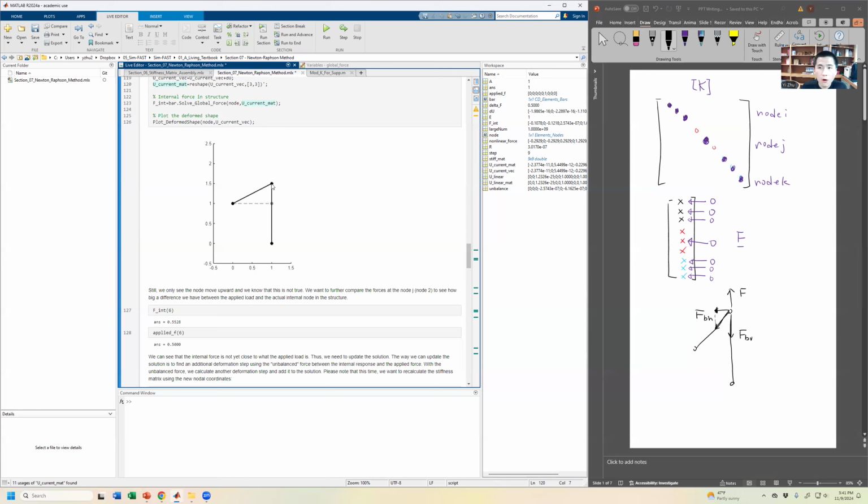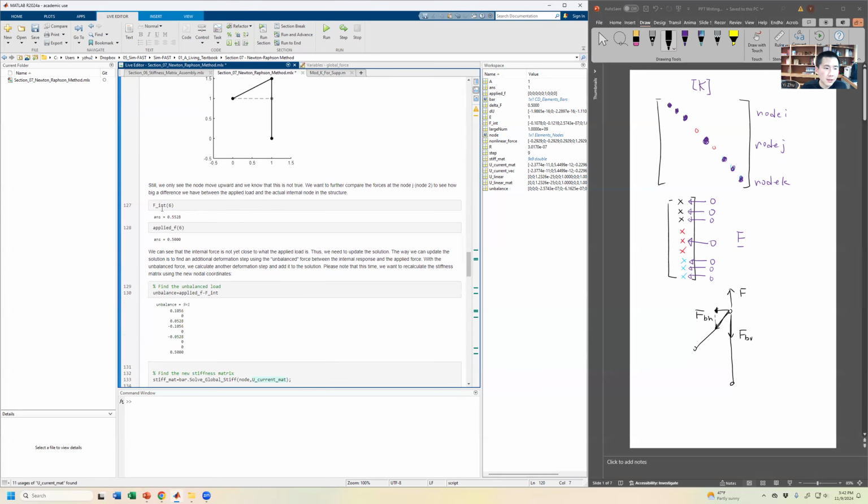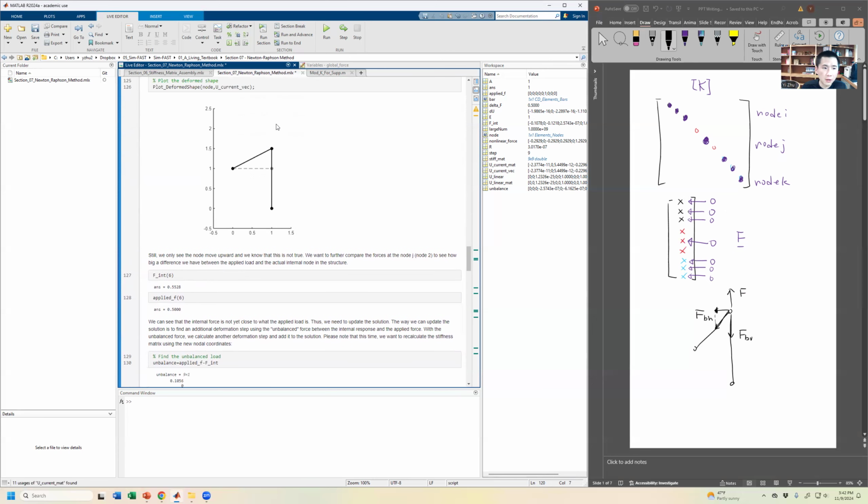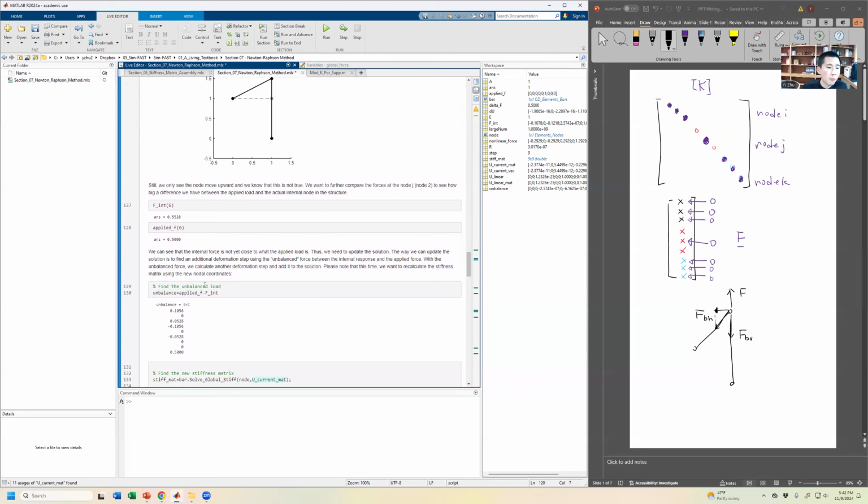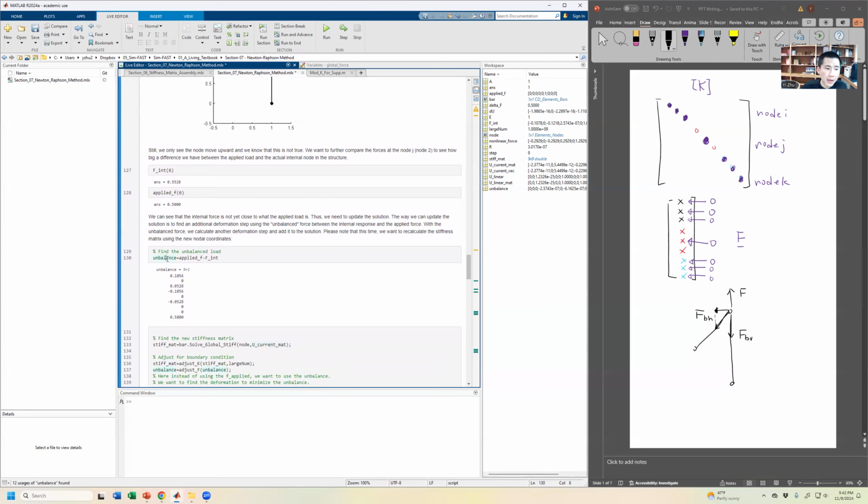This horizontal bar is stretched and it's going to generate some unbalanced force in the left direction. So we can see that in the 6th index of the force vector. So basically in the z direction force, it's not balanced out perfectly. There's still going to be 10% of error there. And the most significant one is this unbalance.